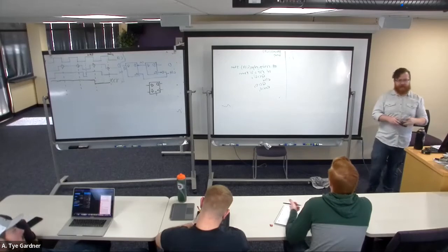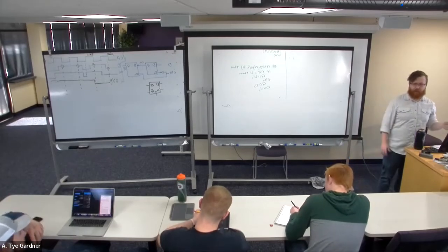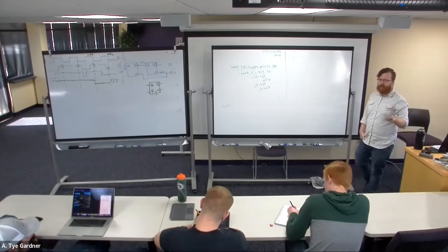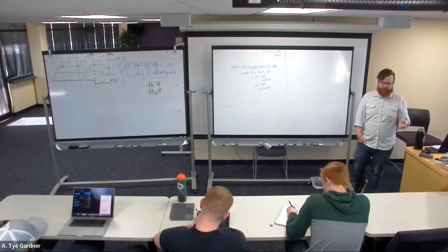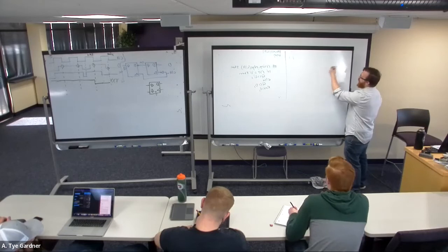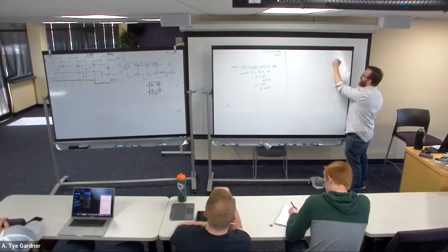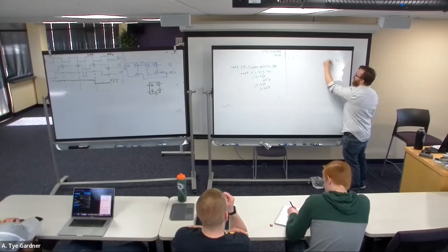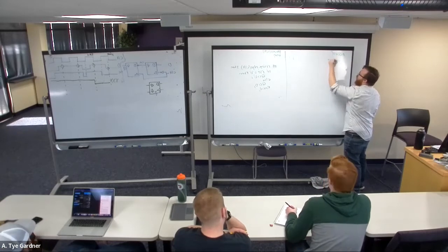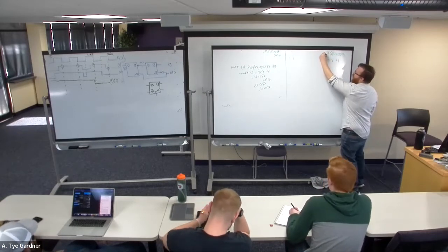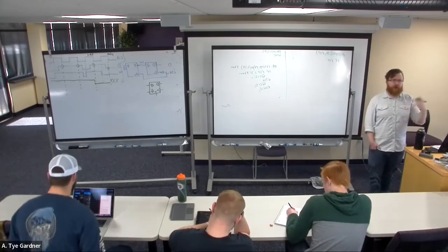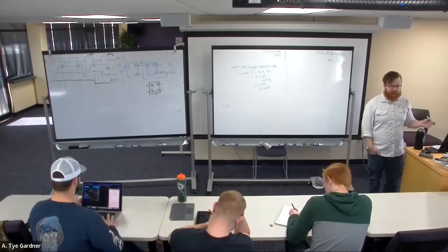However, I tend to design asynchronous resets most of the time because I don't like worrying about the timing of my reset. There are good reasons to use either synchronous or asynchronous depending on what your design is doing. Most of the time, asynchronous resets are completely fine. So if I want asynchronous reset inside of the process, I'm still going to do the same thing, but I do need to write the process, otherwise I will miss an important part. The process I want to run on clock or on reset, because I want the process to be able to respond to reset. That makes it asynchronous.